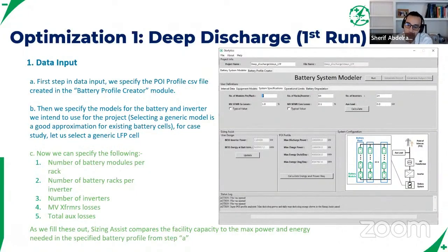It's not just about what the inverter OEM is doing, but also there are a lot of battery integrators out there that put together really sophisticated fusing schemes to allow higher duration systems. Definitely not anywhere near the 100-hour duration system you have here, but when you start getting into 6-hour to 8-hour and beyond, you start needing more sophisticated systems, especially if your inverter has a common DC bus.